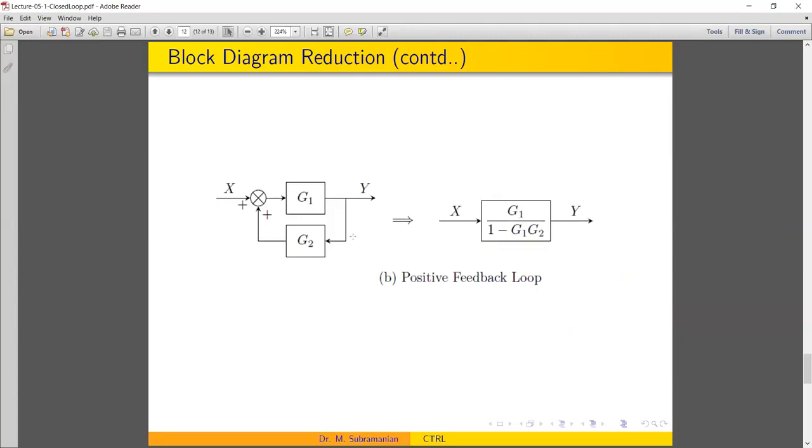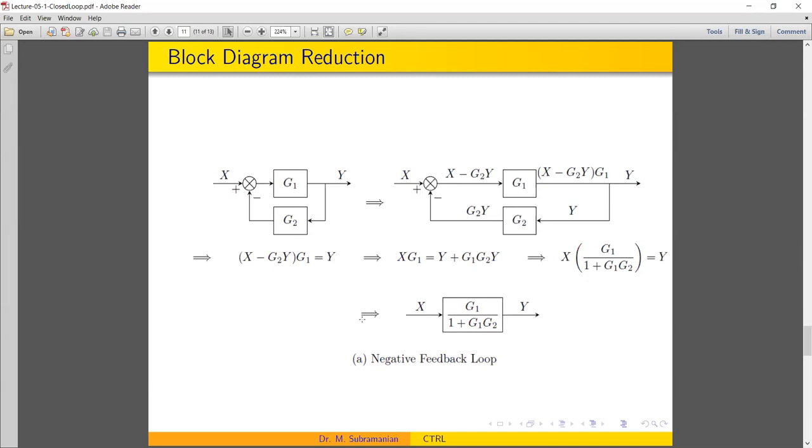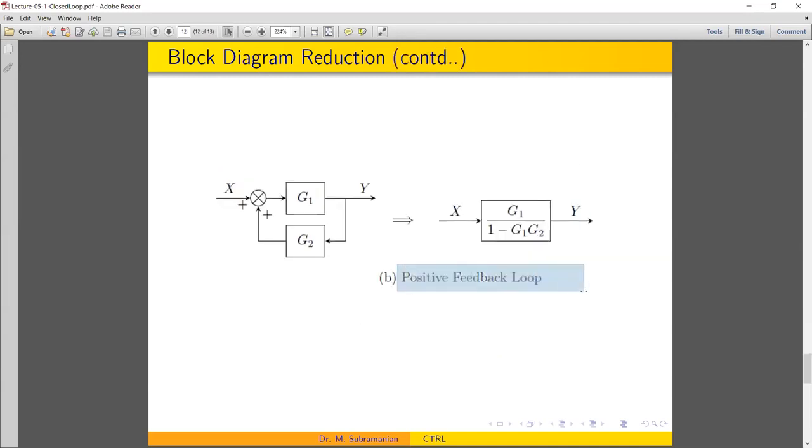Likewise, you can also prove that for a loop of this fashion, what is called as a positive feedback loop. But in a control system, we'll have only negative feedback. Only with a negative feedback can we have control. Otherwise, suppose this information is again added with a set point, what will happen? The denominator will keep going toward minimum, and the output will keep on increasing. So you won't have any control. Instead the output will keep shooting up. The feedback loop is simply a negative feedback loop. There is no positive feedback. Positive feedback will keep increasing the output, whereas we want to keep the output steady.